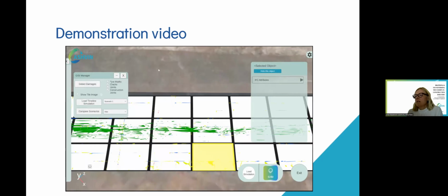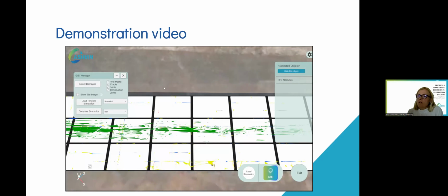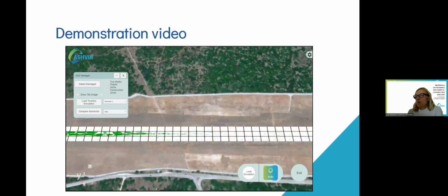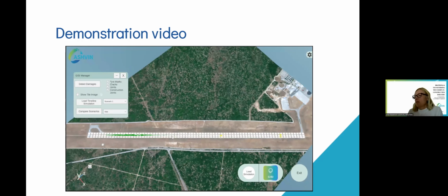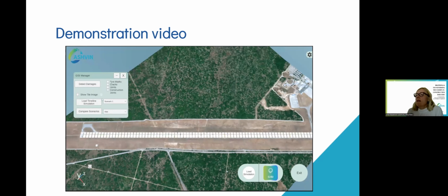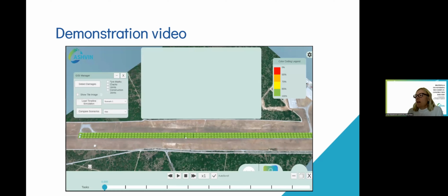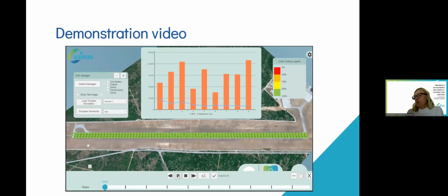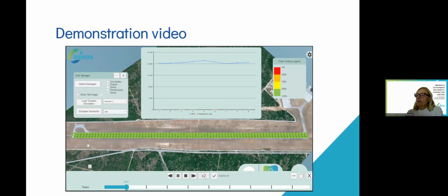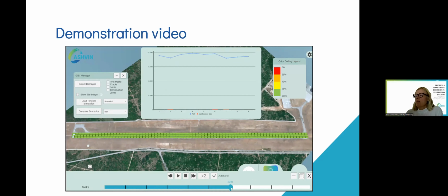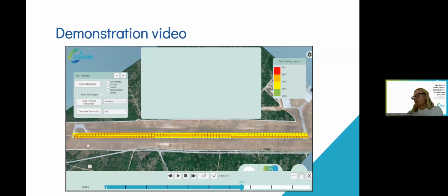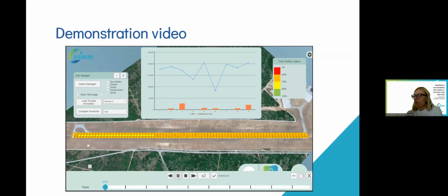And then the next is that we want to load timeline scenarios. So this is now the condition assessment at the end of 2022. And we are now predicting different development of those damages over time by integrating 2 maintenance scenarios. The first scenario is avoiding the risk and always keeping the performance level in this green area. Whenever the PCI threshold of 85% is reached, a minor repair is applied.